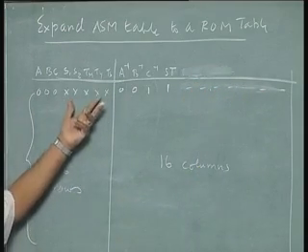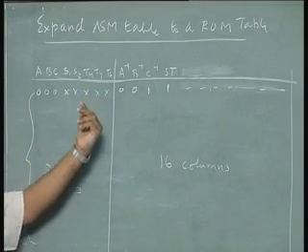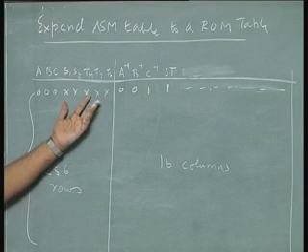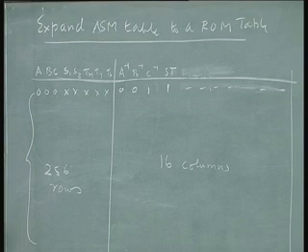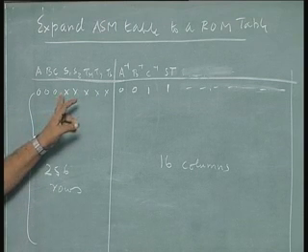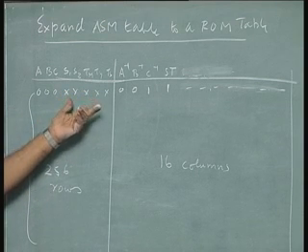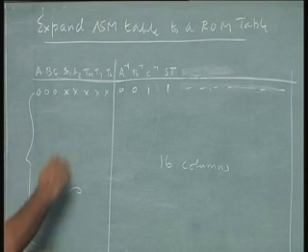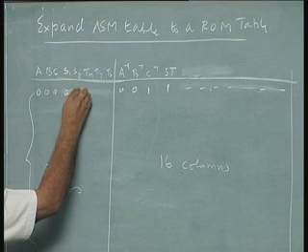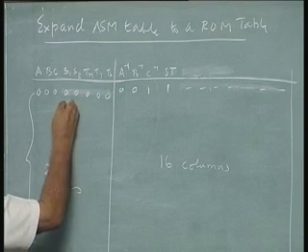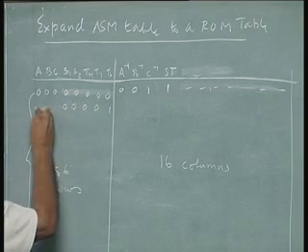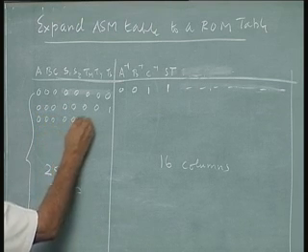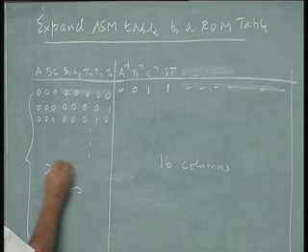Or if you want to write red and all that, I am not going to fill this. This is just an example. Now this XXX will not hold in a ROM table. In the ASM table I can have an XXX because I am only looking at the conditions for the next transition. Now these 5 X's have to be expanded into 32 rows, for 5 inputs, so I will have to start with 00000, 00001, and so on, for 32 rows.